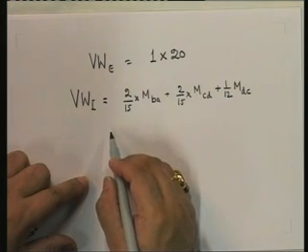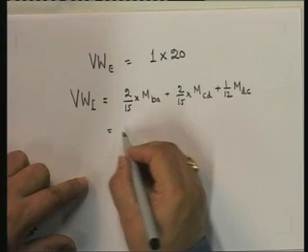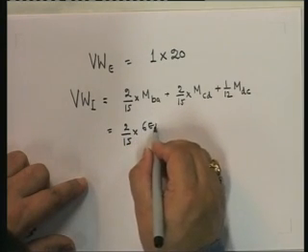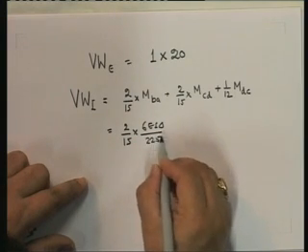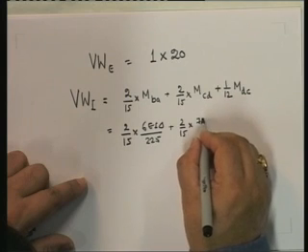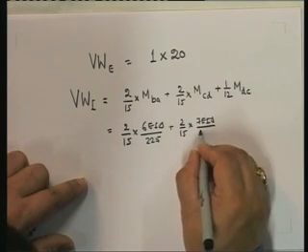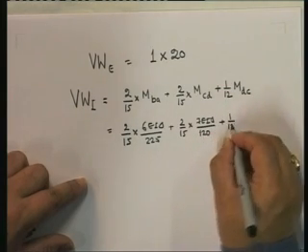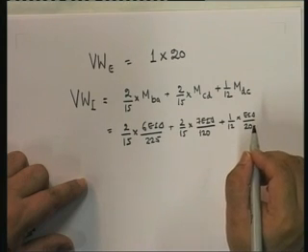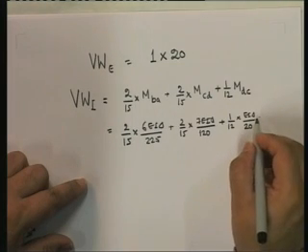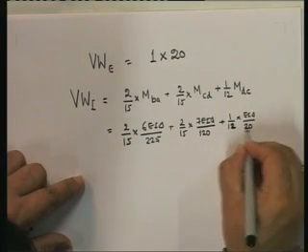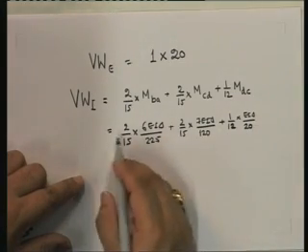Okay, so MBA, so this one then becomes equal to, if you look at it, 2 by 15 multiplied by 6 EI delta upon 225 plus 2 upon 15 multiplied by 7 EI delta upon 120 plus 1 by 12 into EI delta upon 20. Okay? So now this, if I take it through, you will see this is equal to this.